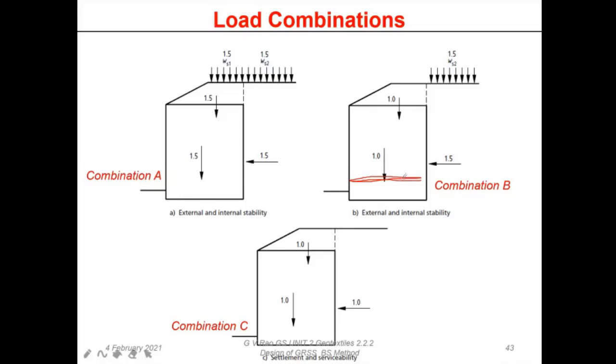Normally phi is the value of the angle of shear resistance. So tan phi is the soil-to-soil value, and delta is the abbreviation you are going to use for the interface friction. The actual thing is that we are essentially going to use sandy soils. So what friction can we generate right now?